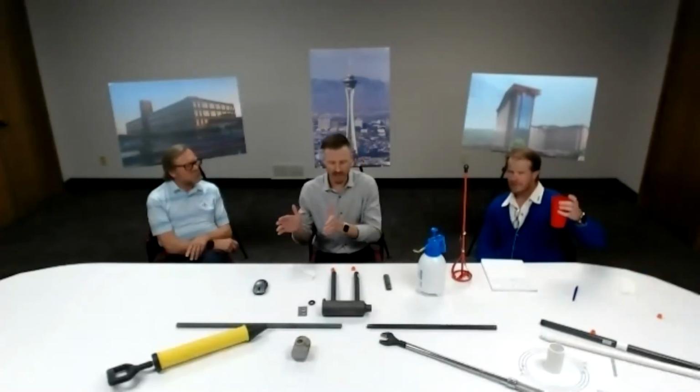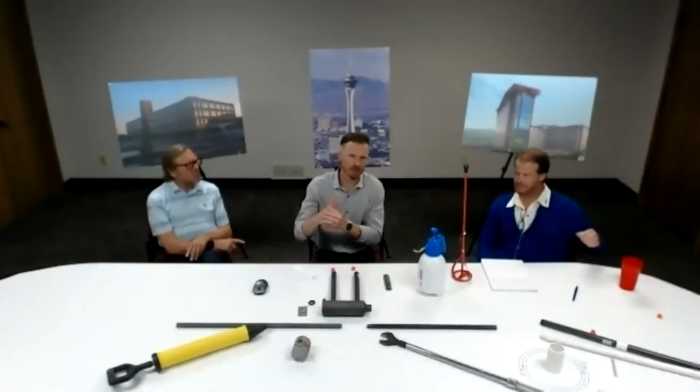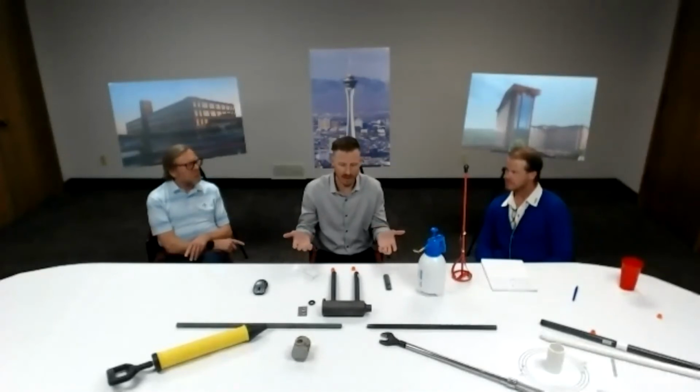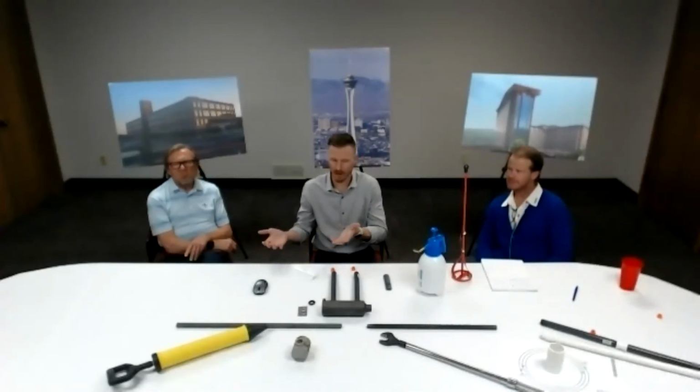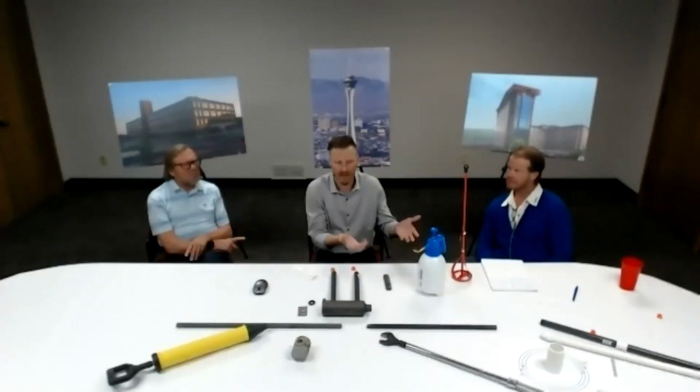So usually off of the third point near the column, that small cantilever of the column can support the weight of the slab, and sometimes support the dead load of the slab. So our coupler works no different either way. It can support that weight. It would also have to be reshored if it was in the middle of the slab.